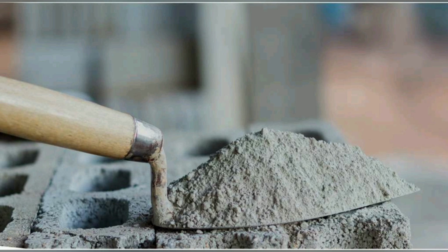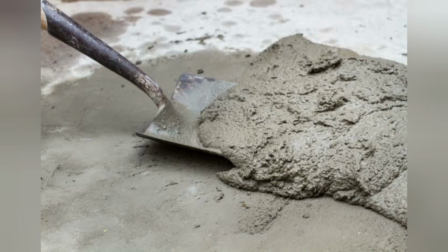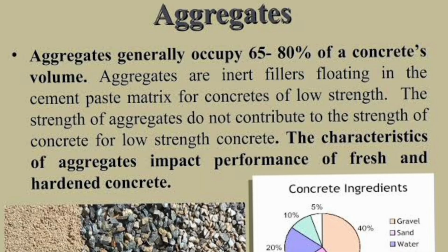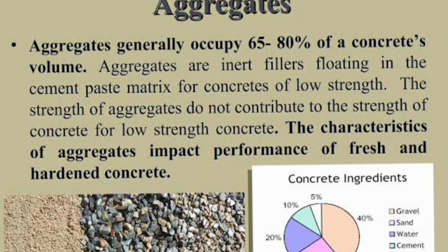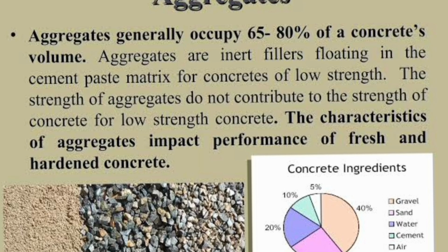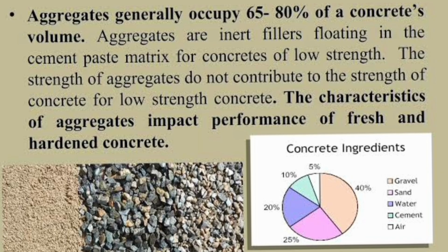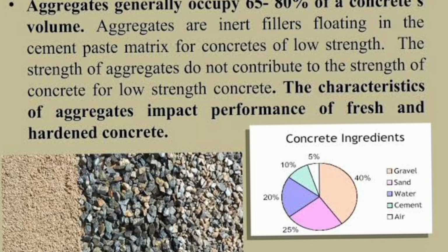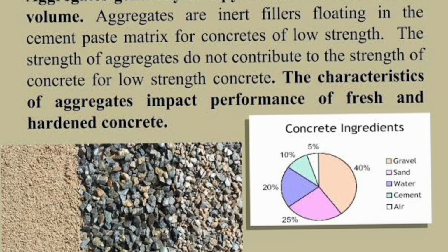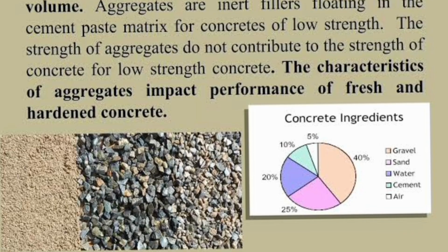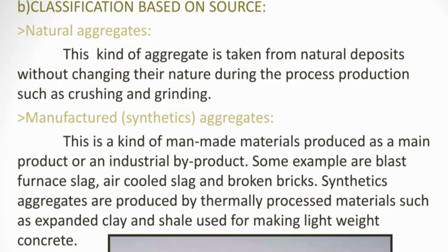This is why you must always check the manufacturing date on cement bags and perform regular tests to confirm its strength. The aggregates you use play a surprisingly significant role in the final concrete strength. While the cement paste is the glue, the aggregates are the bulk of the volume. Their properties matter immensely. First, the strength of the aggregate particles themselves must be higher than the concrete strength you're